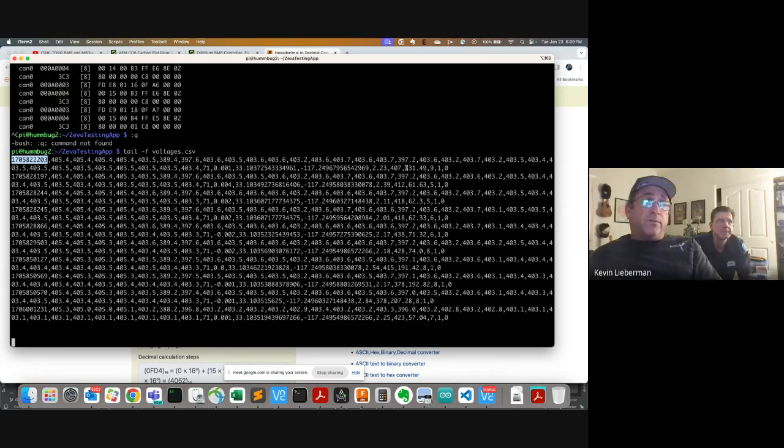Right. This would have been really valuable on the yellow bus because we had times when it wouldn't charge and we didn't know why, because there is no display in the yellow bus right now. There may be a fault light that comes on to say there's something wrong, but we don't know what it is. But any number of things could be wrong, causing it not to charge. So with the data acquisition, that would just tell you where and when it stopped charging. Yeah, well, you'd have the temperatures of all the batteries, and then maybe you'd have the fault code in here, which would say, I'm not charging because battery number 3 temperature is too high. That was one of the things that happened recently.